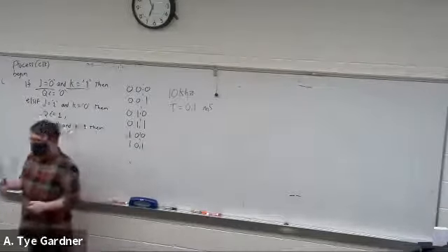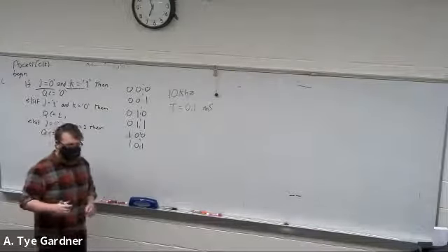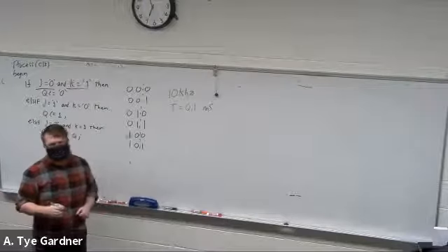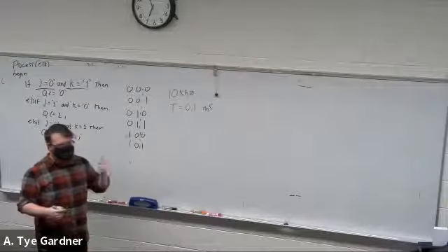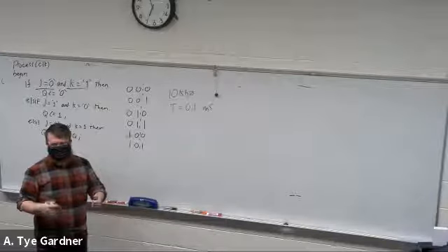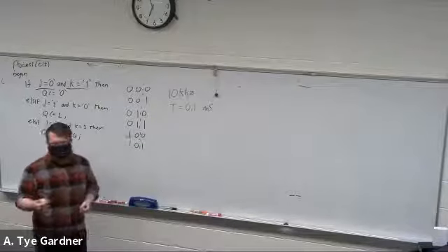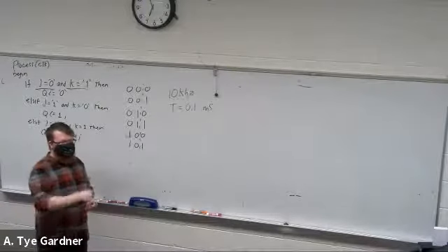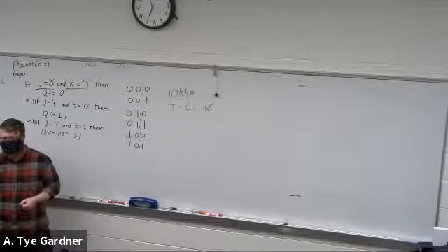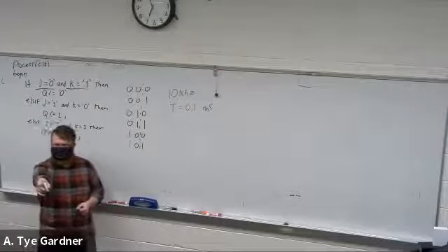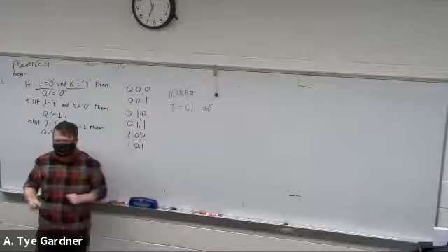So now let's say, as I'm going to in a lab, that you're asked to build a garage door opener using digital circuits. And it's only going to respond to the garage door button if you hold it for 1 second. So if you accidentally bump it, I'm not going to do anything. If you sit and hold it, I'm going to react. How many clocks do I need to count to get to 1 second?